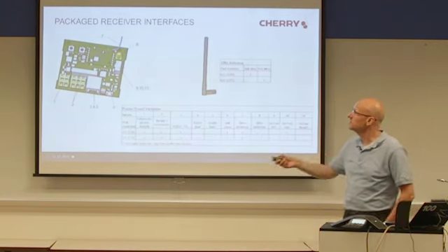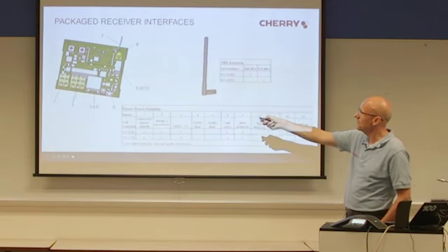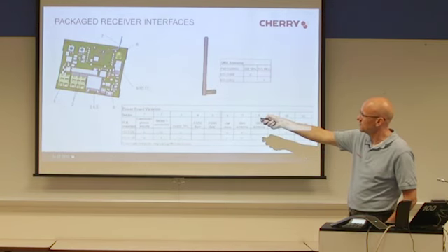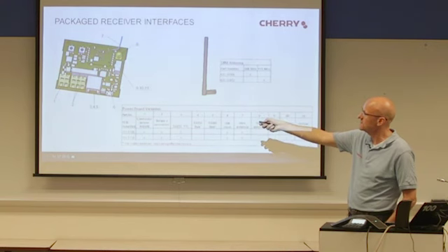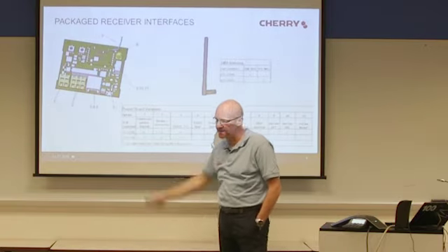And also the information of the pairing button, pairing start, pairing stop, the LEDs, switching the outputs, switching the interfaces, all this is handled on the power board, not on the RF stamp.